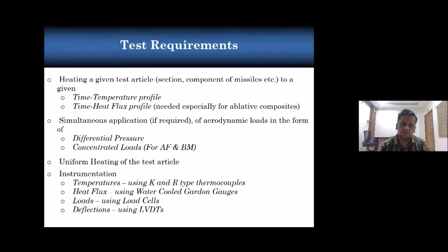We also determine what type of fixtures are needed, what type of heaters are to be designed and realized, and whether it can be done with available heaters. All of this is given in a standard format. Apart from temperature, we can apply structural loads in two ways: either a differential pressure application, or concentrated loads, which are applied mainly to simulate the axial force and bending moment on the airframe sections.